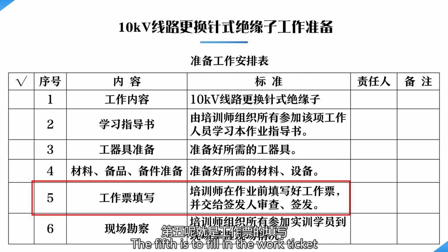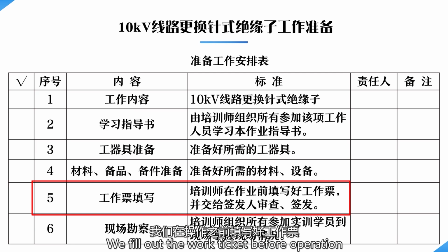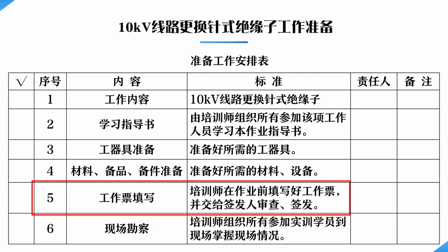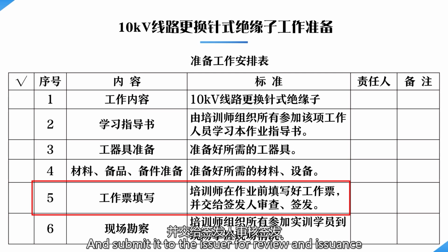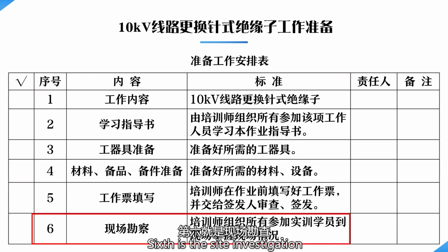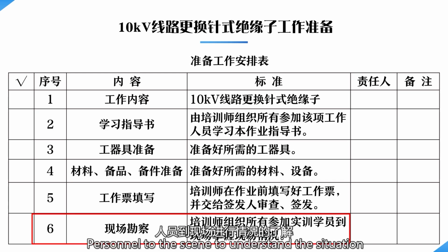The fifth is to fill in the work ticket. We fill out the work ticket before operation and submit it to the issuer for review and issuance. Sixth is the site investigation. We have to organize all the participants to go to the scene to understand the situation.